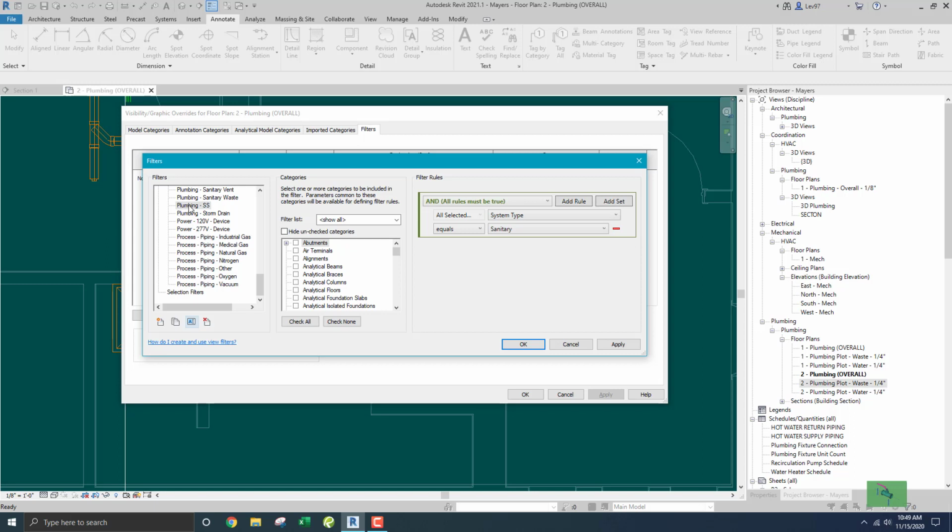But you'll see on a lot of documents that even though there's no water closet connected to the system, it's labeled as sanitary sewer, and it's okay. But if there's an argument or a discussion about it, it would be true that the proper labeling would be sanitary waste has no water closet.